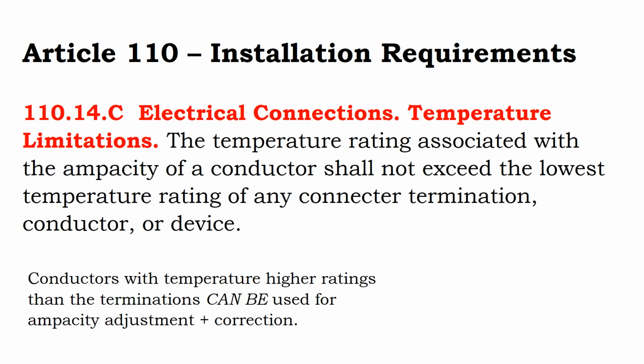All right, so 110.14(C), electrical connections with temperature limitations. The temperature rating associated with the ampacity of a conductor shall not exceed the temperature rating of any other connector, termination, or conductor of any other device on the circuit.